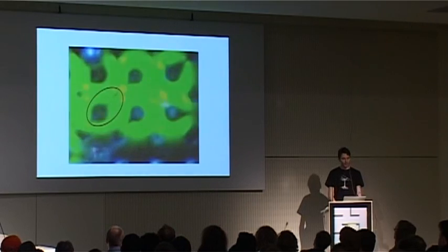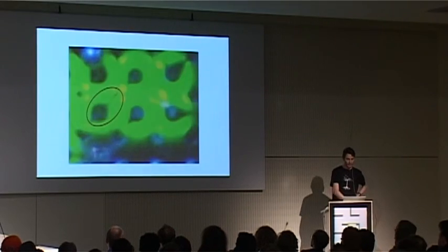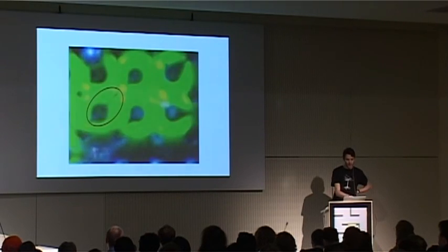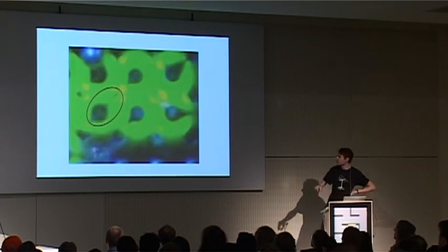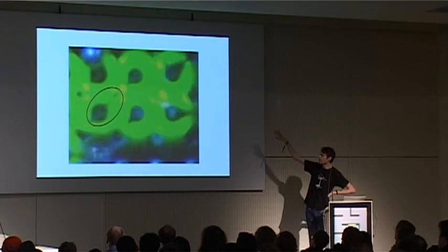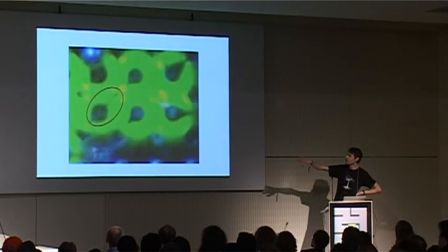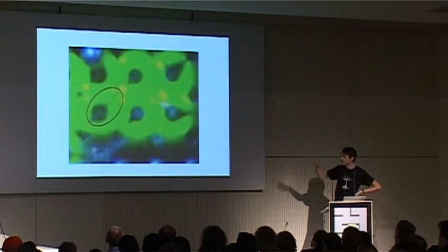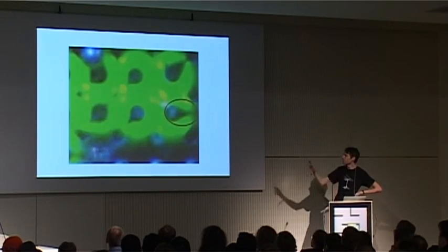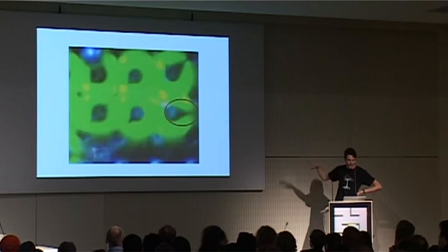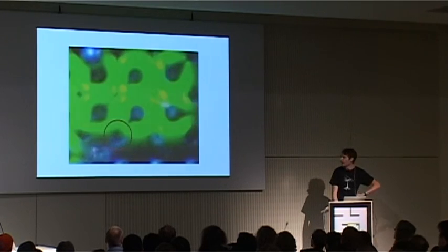What I noticed is with the backlight, you can see that at each point where a ball is missing, you can still see a small connection. In this particular case with this ball, the connection is going to the top right. In this particular case, it's going full right. And with my pad, which is this one that I wanted, I didn't see it going anywhere, so I could take a guess.